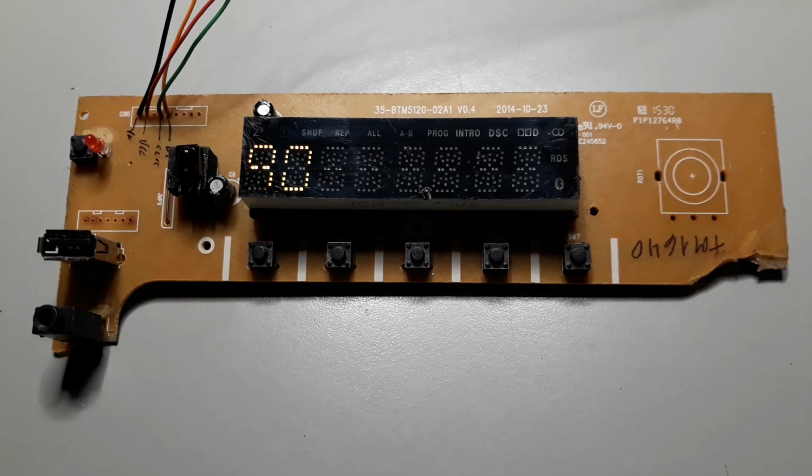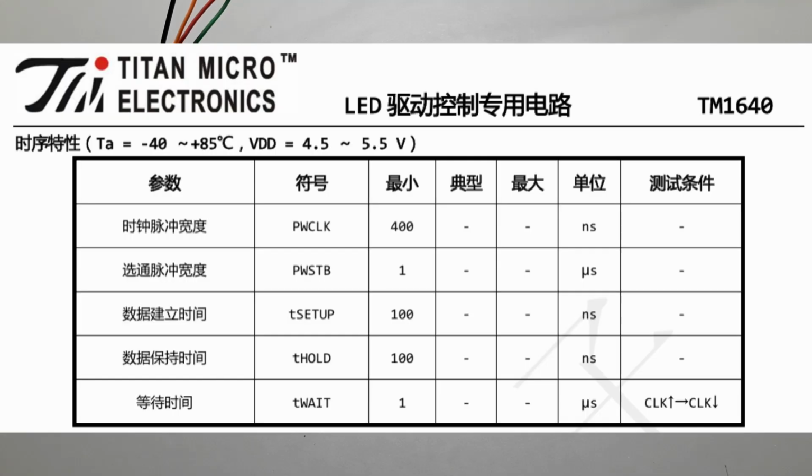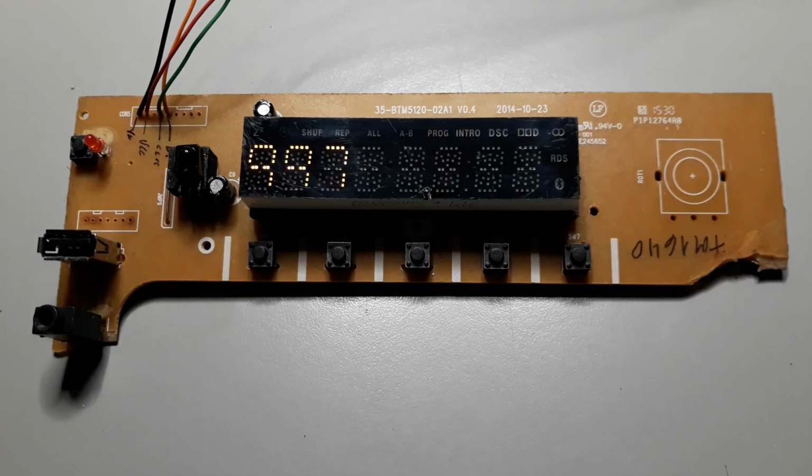I didn't spend much time on the timings present in the datasheet, and this may be the reason I had trouble sending a 16-byte burst to fill everything on or off in auto increment mode. So I used direct memory address writing. I observed that if I send a text sequence, everything works, but if it is all zeros or ones, it sometimes fails. I believe this is due to an incorrect time configuration in the communication protocol.